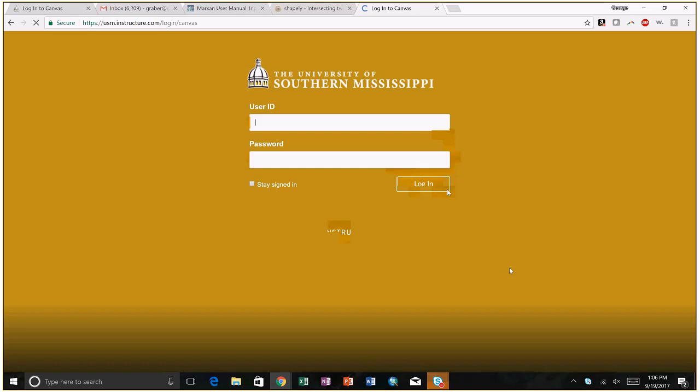All right. Any other questions? So don't send me the latitude and longitude. Send me the northing and the easting. Okay. And if you do have the option, make sure you choose WGS84 as your datum. It is the default, and it's really the only one there that we've talked about. Some devices will allow you to choose other datums like NAD83, which is very common. WGS84 is what we're going to use. So that's the datum.